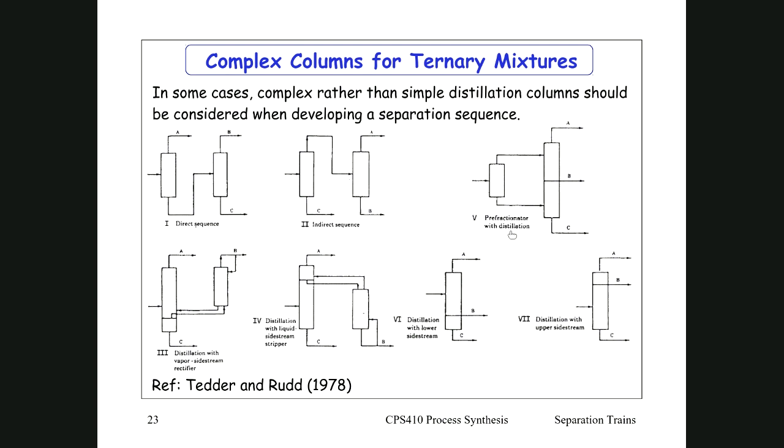And this is something that you can apply by putting in a septum or a divider that runs downwards through the column in this way, so that you've got trays on both sides of that separator. And that way you can put in these 2 feeds and get separation.